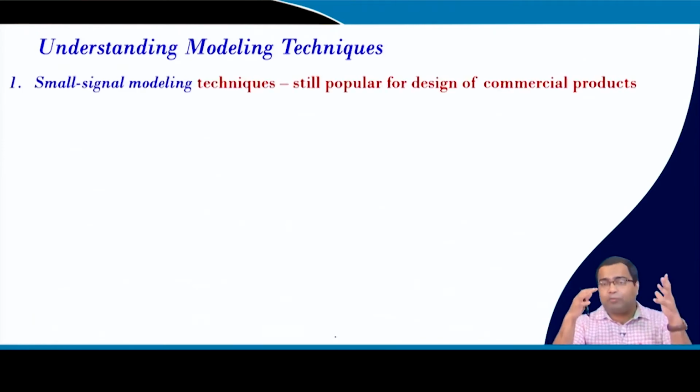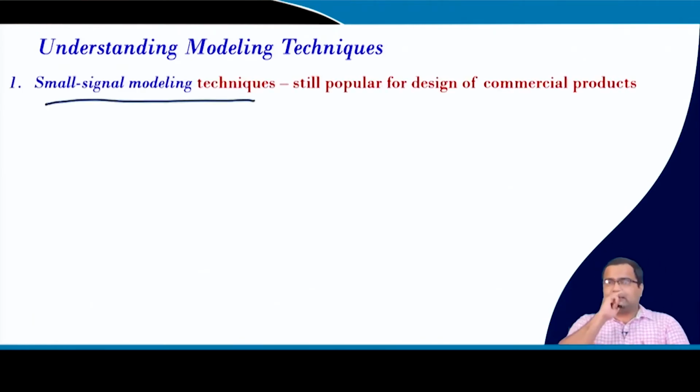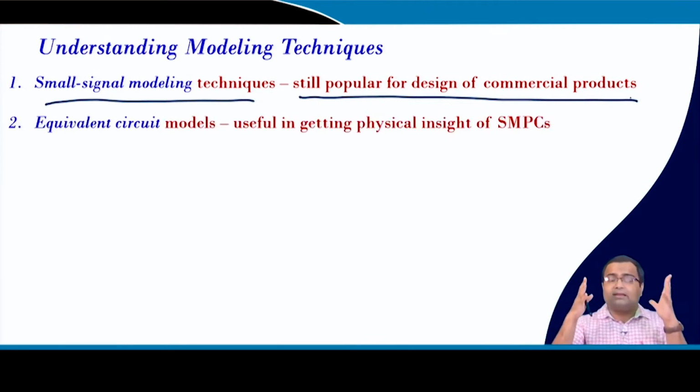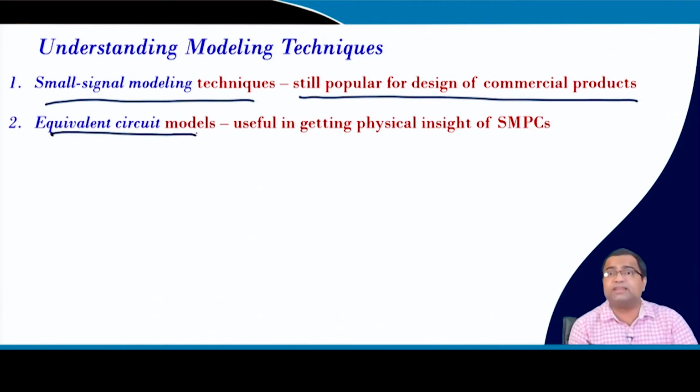Then we learned in the modeling technique, the small signal modeling technique was the simplest one, because that gives us the transfer function and we are familiar with the different control to output transfer function, impedance, and this kind of concepts are still dominant in commercial products, and you will find a lot of application notes available which use a transfer function based compensator design, and each industry provides application notes related to their product and you can learn from there. But what we learned, and there the equivalent circuit model concept was very useful, that gives us physical insight in terms of output impedance, audio susceptibility, input impedance.